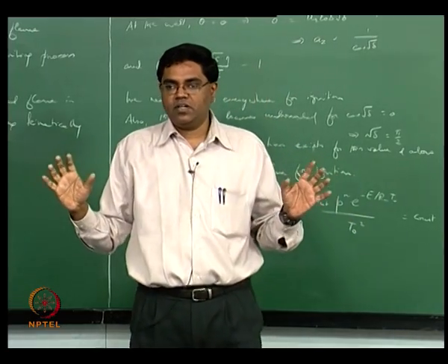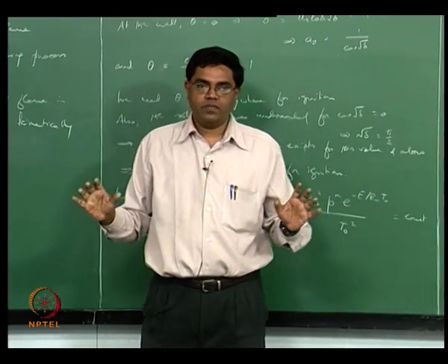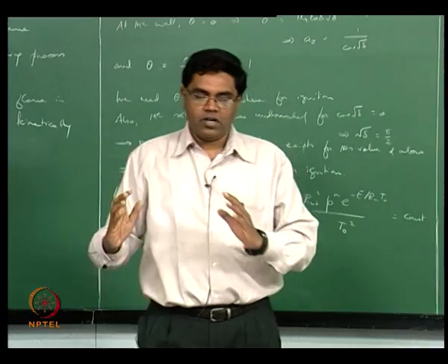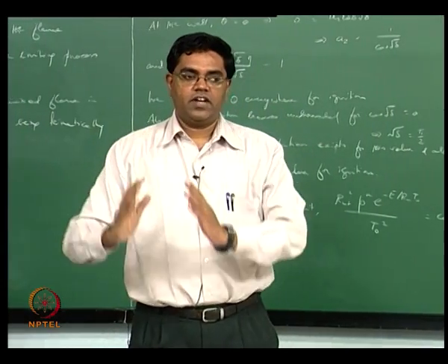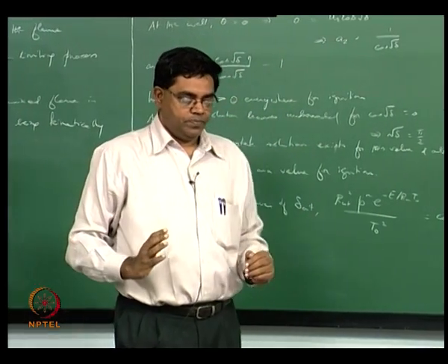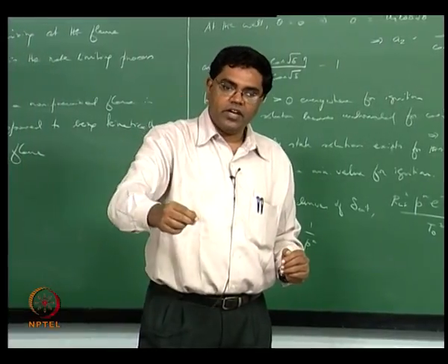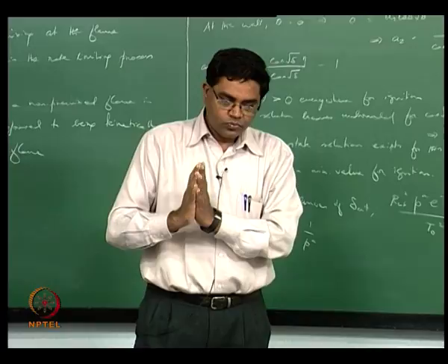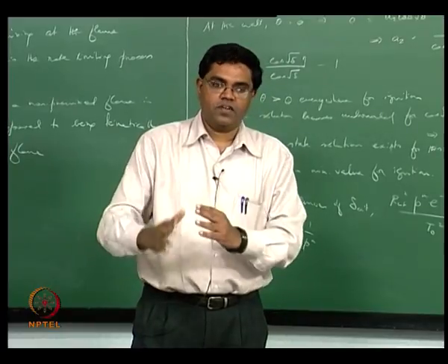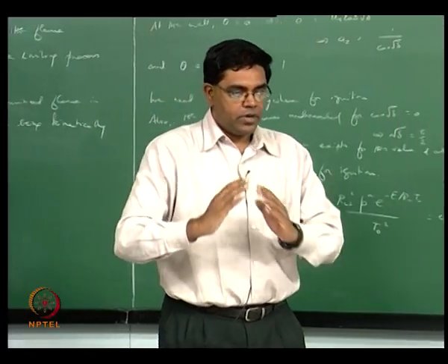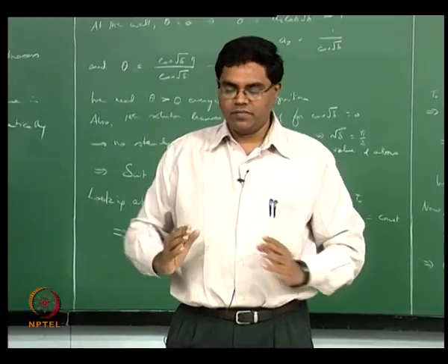That's another matter in a gravitational field, and that's partly the reason why you're seeing this kind of a shape for the flame, and also the reason why the flame looks elongated, besides the diffusion process itself causing it to elongate when compared to a compact conical premix flame.